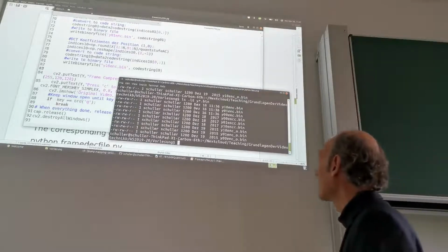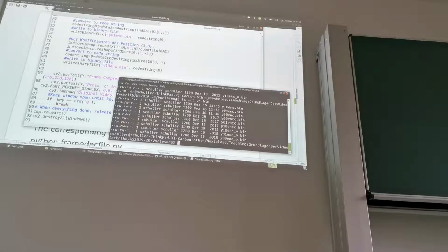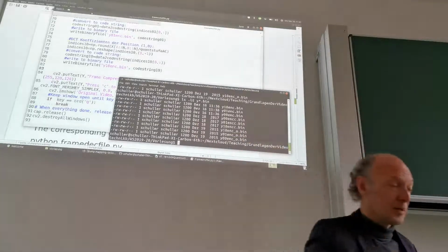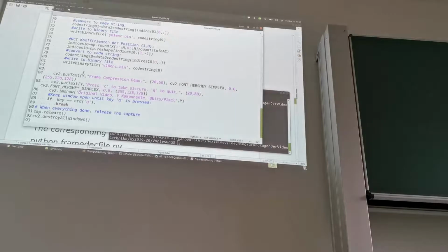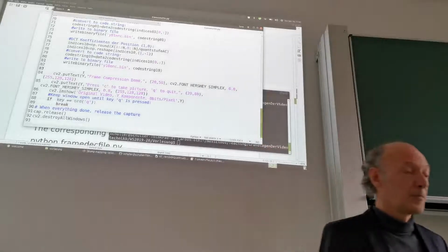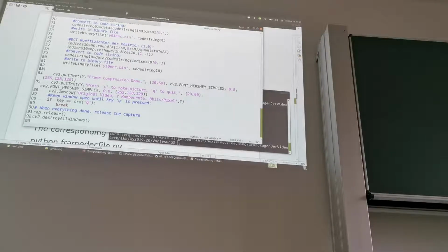So here we indeed have 4,800 indices per coefficient phi. And this comes from the size of our frame. Again, we have this VGA size frame. So we successfully generated our files, and the sizes look okay. I didn't compute exactly what we expect, but it roughly sounds okay, because we need to do the downsampling by 8 horizontally and vertically. So it's a factor of 64 compared to the total number of pixels. Next we need the decoder.